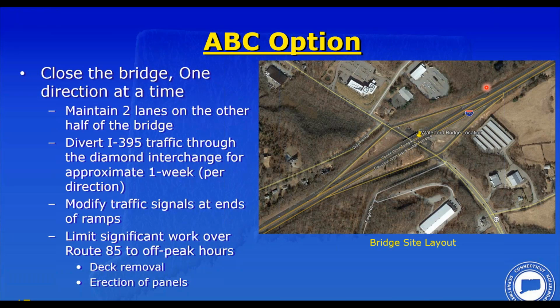So we're actually going to take traffic, run it down the ramp and back up the ramp, which is a very handy detour when you have a diamond interchange. The idea would be to do a deck replacement. This is where we had honed in on a deck replacement as the structure type that we're going to use.